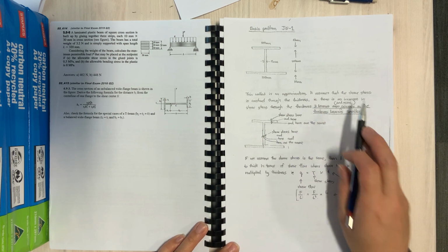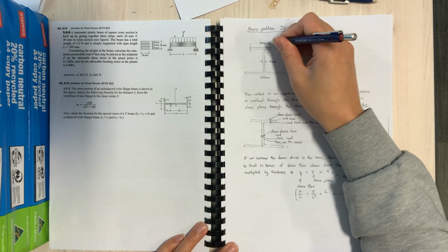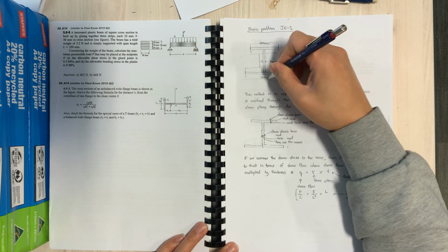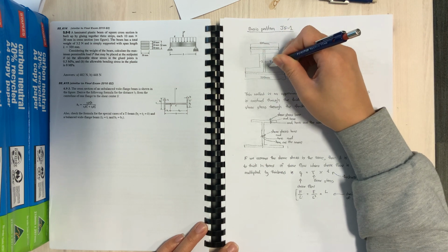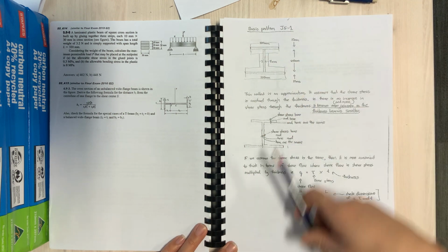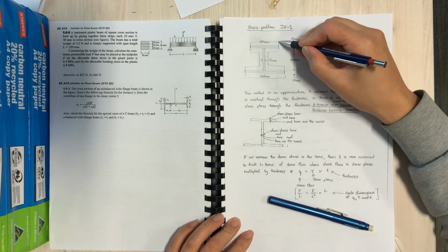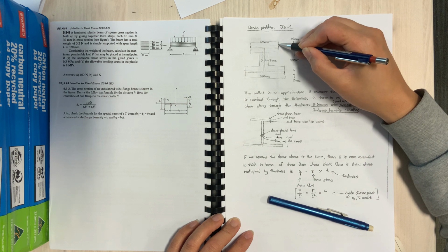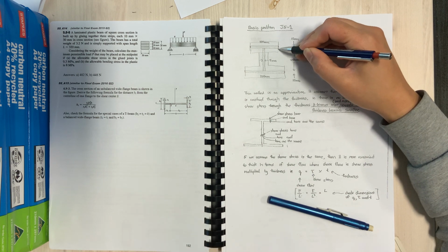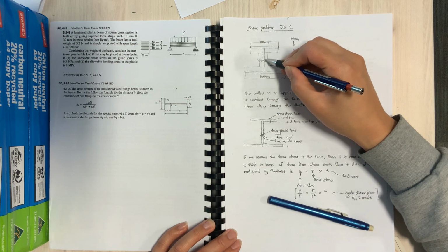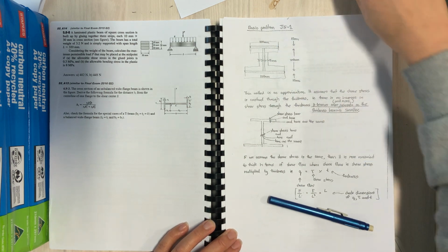So you may not like it. You may be saying, hey, I've got a very thick section here, and I may not like to use the thin wall assumption because I just don't want to. You can always use thick theory, but with thick theory, you're assuming, firstly, that the flange does carry vertical shear, and secondly, that there is a variation of shear stress along the thickness.